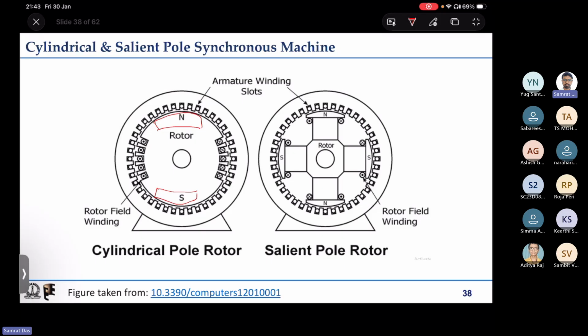So can there be a quantitative thing like this? Actually if we try to compare the energy densities of magnets and field winding, so some iron core coil with some field winding, then the energy densities that are possible are actually quite different. Permanent magnets have energy density as high as, I forgot the numbers, but they are at least some 8 to 10 times compared to one electromagnet. And what do we mean by energy density of permanent magnets?